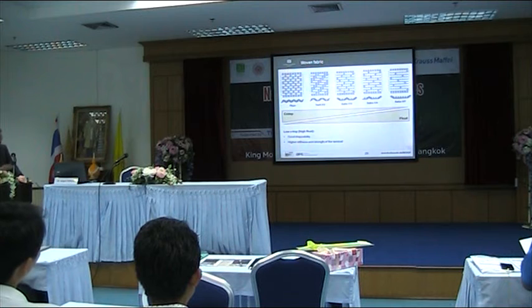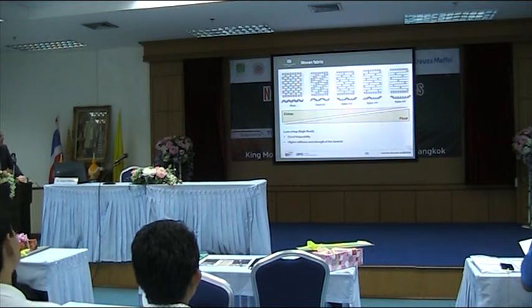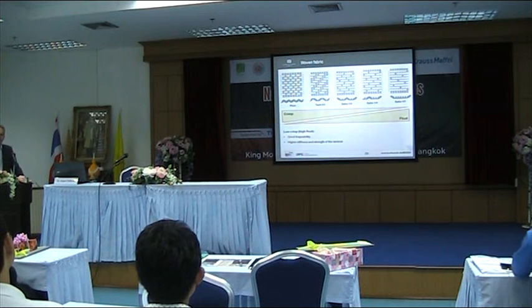So woven fabric, this is the typical structure of the woven process. Typically it's plain weaving, and the crimp goes down. Crimp means the curving of the fibers. As the crimp goes down, the bending stiffness is lower, but the lower the bending stiffness, the better is the drapability and the flow.